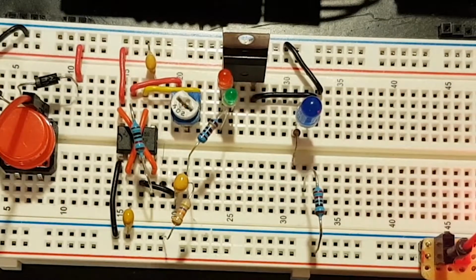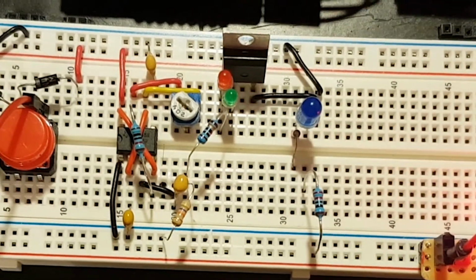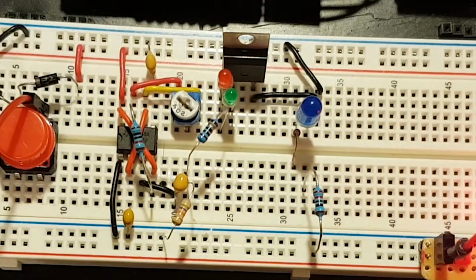Next on our list we have the Schottky Diode. They can be in a similar casing to the silicon diode, but also come in different TO packages like the TO220 here on the breadboard. The Schottky is constructed the same way as the silicon diode, except one side of the silicon has a metal contact. This increased conductivity makes for a far lower forward voltage than the silicon diode, so you'll only drop in between 0.15 and 0.46 volts as opposed to the 0.7 in a silicon diode.